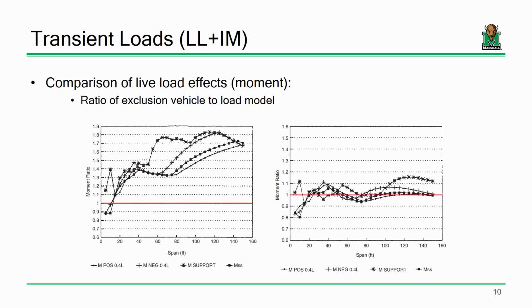If I have a moment ratio of 1.1, that means that the bridge is seeing 10% more moment than what we're designing it for. You see what I mean? So this was bad. We were dealing with moments that were 80% more than we as engineers were computing. That's bad, because over time, the loads that those highway bridges were seeing were heavier.